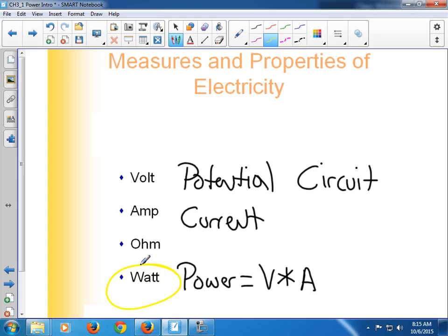See, it says 500 W. 500 W ATX. This is a 500 watt ATX power supply. It's the big bold letters. They're not trying to hide it from you, just so you know. So this one in particular can do 500 watts. That means that's the max that can come out of these wires to power your PC. And we're going to have to learn how to calculate what a PC actually needs, because in the case of this one, the PC required more than 500 and kept shutting devices off. It couldn't power everything at the same time.